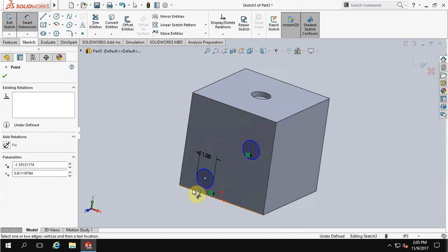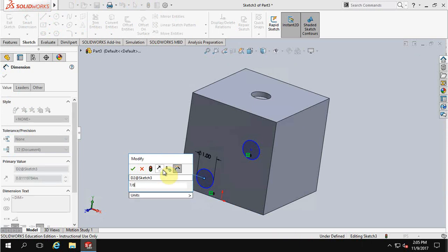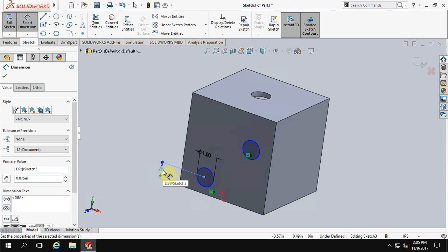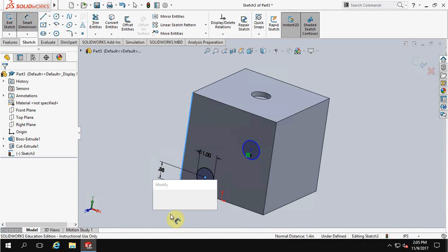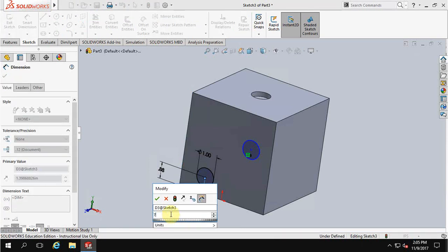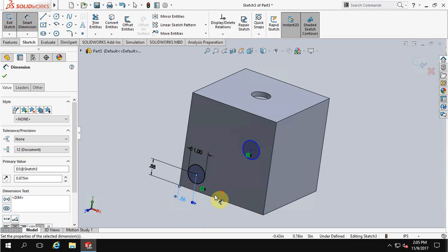I can then continue to do the smart dimensions as I've done before. This should be 7/8 from the edge. Solidworks will do fractions just as Onshape does. It'll do simple equations. And it'll pop itself into position.